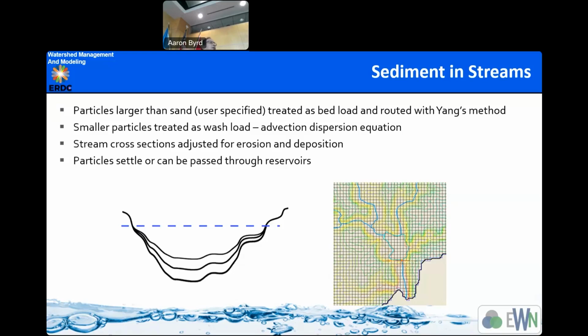The suspended sediment we define just like overland, but in one dimension it's an advection equation, which is again a function of depth and unit discharge. The derivatives of those in time and space are balanced in mass and continuity with the source of sediment and the lateral inflow at that particular place.